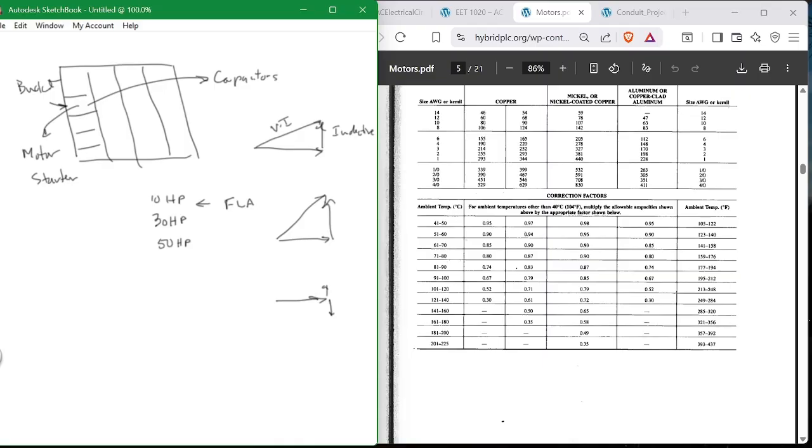Could be 10%, but if it's over 10%, then you're starting to lose efficiency. But you say, the load varies. Yes, it does. So basically, this is an average of all of them. You try to fit it as best you can based on the load in your factory. So you do a power factor study, and then you might add capacitors, you might not.